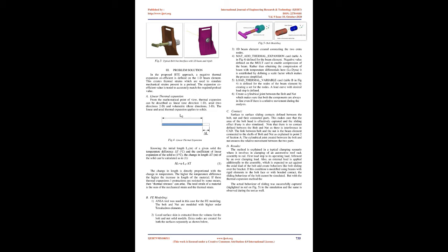Since bolts are sliding contact thread devices, most of the energy spent tightening them is dissipated by friction. In general, about 50% of the energy goes to friction under the bolt head, 40% goes to friction in the threads, and only about 10% goes to creating tension in the threads. Fortunately, rotation of the bolt head relative to the parts being bolted together is a good measure of the tension in the bolt.